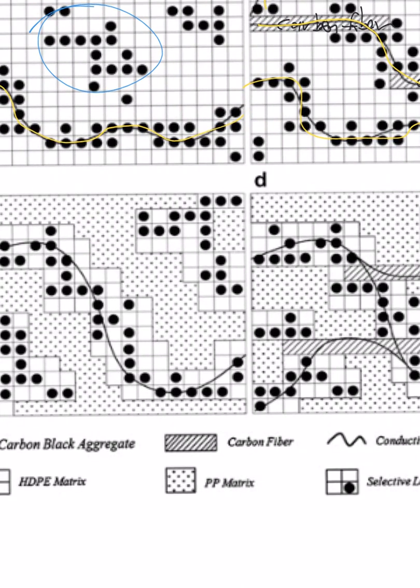And then they do other things in which they have a polypropylene matrix, and we still have the polyethylene here, and we still have the carbon black doing its job and allowing current to flow through, or maybe around, depending on where this all goes. So you're looking at blending these different polymers in this context to try to make the use of the polyethylene a little more efficient. The polypropylene has a much higher melting point, so when the polyethylene trips, the polypropylene just holds it in place. It doesn't let it move or sag under the influence of gravity, which is important in this context.